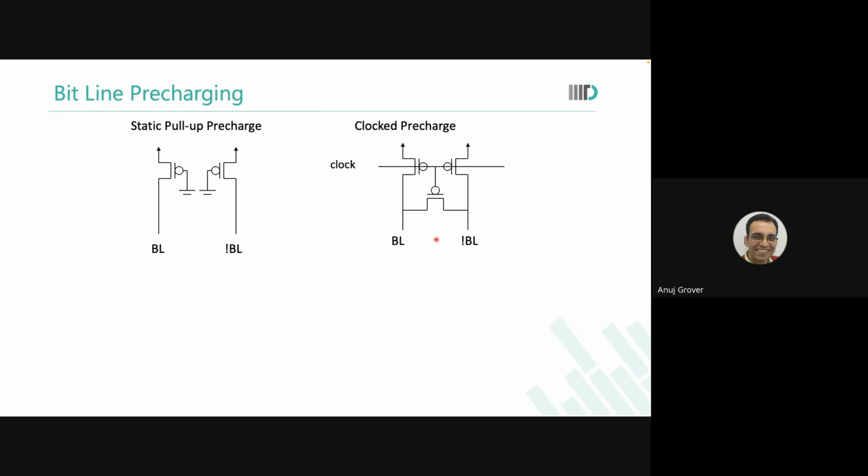All of you know RC delays. And all of you also know that RC delays lead to an asymptotic charging of capacitances. No capacitance is really fully charged to VDD. You come very, very close to VDD, but to really come to VDD, you will take infinity. Now, you can't wait for infinity after every cycle. So you say, okay, this is the time I'm giving you for precharge. After that, done. So what could happen?